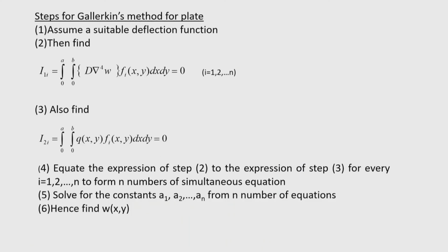Okay. So, let us discuss the steps of the Galerkin method. I will give you the systematic procedure to be adopted in the Galerkin method for solving the plate problem. The first step is to assume a suitable deflection function. The deflection function can be assumed with a trigonometrical series, or with a polynomial function. It depends on the choice of the analyst, or it can be assumed as a combination of these.